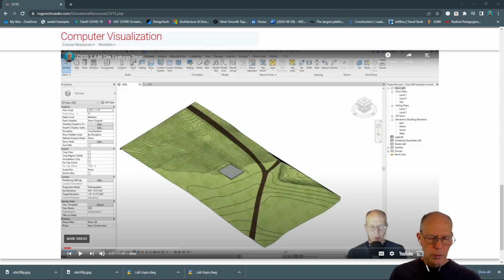Now we can substitute our site topography with grass, as you can see in this illustration here. We're going to put in a building pad, which is where we're going to site our building. And before we even do both of those, we're going to extract some information about where the road is by using the satellite image and creating what's called a subregion. A subregion is something that can have a different materiality to it, but still mate with the existing topographies or that curved surface that we have, unlike a building pad that's just a flat surface.